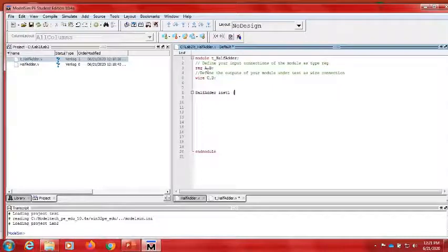First, our module contains the inputs, so I'm connecting A and B here, and C and D here. So whatever inputs are applied to the circuit, A is connected with the X input, B is connected with the Y input of the module because we are using the same placement, and C is connected with the S output, and D is connected with the carry output.